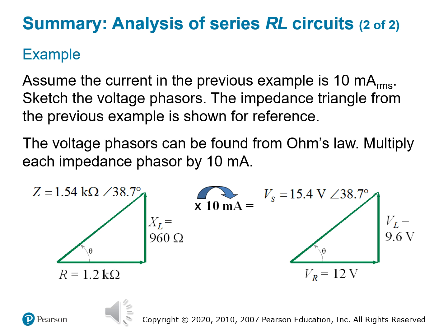These values create the voltage triangle and they mirror the impedance triangle from earlier. This is useful because now you can visualize phase relationships. You can predict how voltage divides across R and L. You can solve RL circuits quickly using phasor multiplication instead of solving differential equations. And because current is the same everywhere in a series circuit, this method is clean, it's direct, and it's scalable.